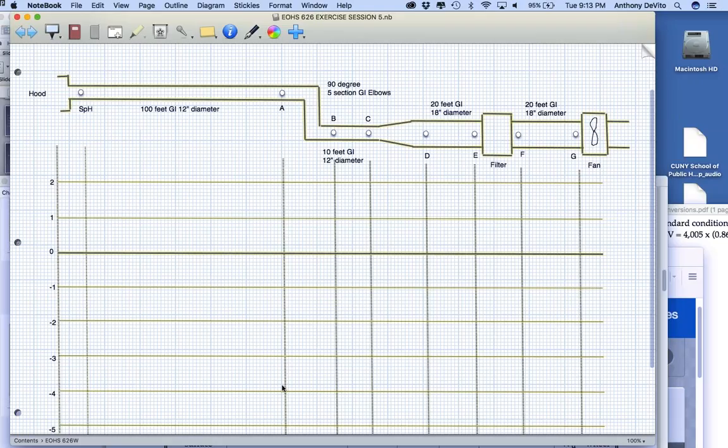So he does some grinding with a Dremel type device. He does some polishing with an abrasive material, and he does some polishing with a very dusty rouge material. So basically, he's producing particulates, and we want to keep those particulates out of his breathing zone. His table is roughly 2 feet deep by 6 feet long, and he's got this equipment in it. So we want to find a hood that's appropriate for a minor grinding operation that's going to be built into this kind of thing. So what are we going to do?